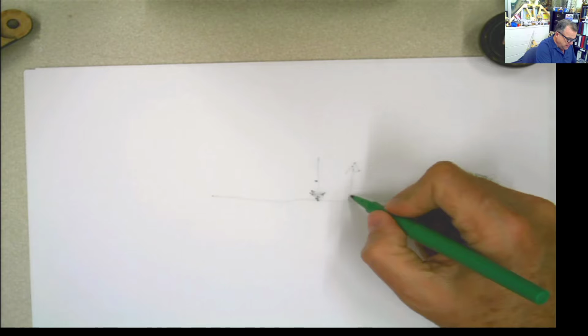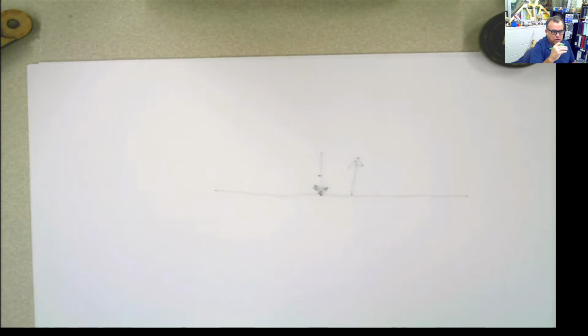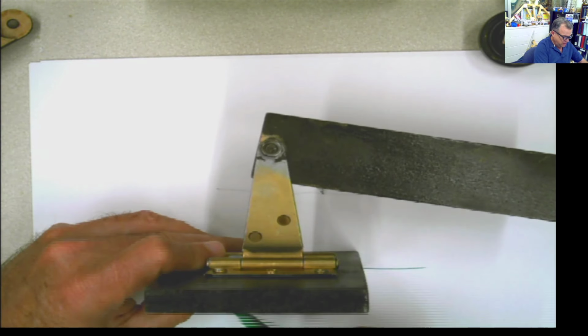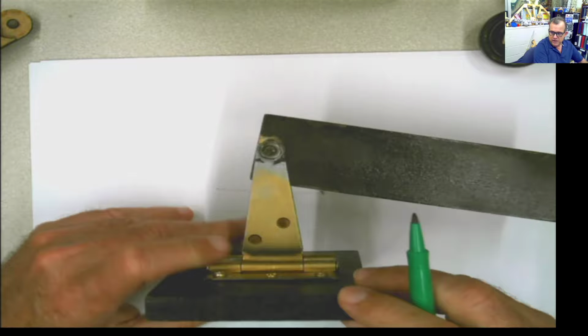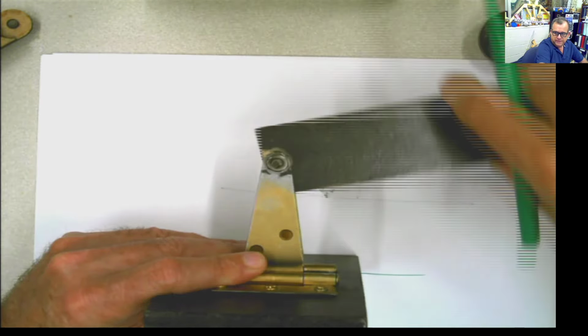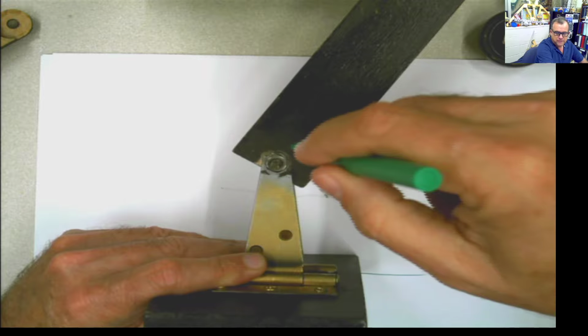What is a pin? A pin is a type of support that provides, in this case now, the object cannot move up and down and cannot move side to side, but it can rotate. There you go. I introduce you to a pin. This is a pin. This is the surface here. So this part is fixed, and this is the structure. The structure can rotate, meaning the moment is not restrained.